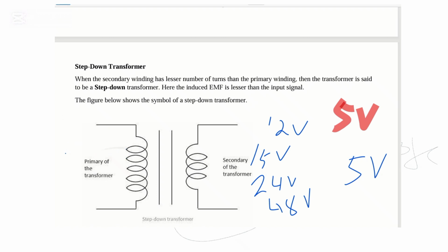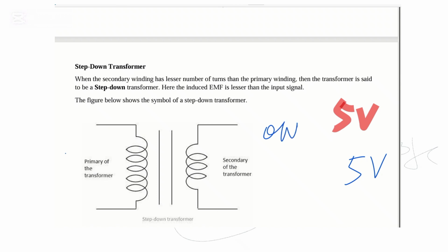Remember, something to note now. How do you choose a transformer when designing your power supply? Number one, know your output voltage. First of all, you know your output voltage. What's going to be your output voltage? So if it's 5, what transformer can give you voltage from 240 close to 5? If the transformer you get is 12, okay, you will work with it. Then you'll get 240 to 12 volt. So when you get 12 volt, now you can design, you can add other parts until you get 5 volt. So you have to know first of all the output you want to achieve.